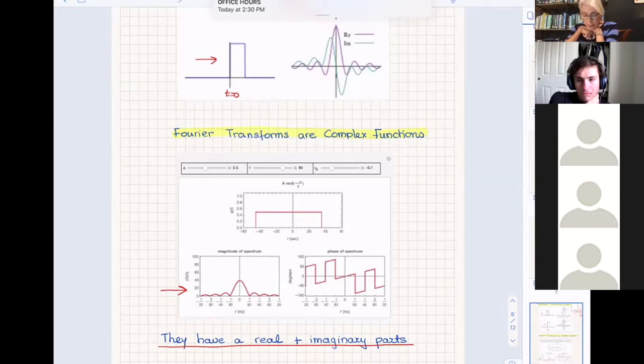in the frequency domain, and let's assume that I want to keep the low frequencies only. What kind of amplitude would I like to have of the filter? How would I like the response of the filter to look in the frequency domain? And how would I like its phase? The response could be like this, the one that I have here, right?